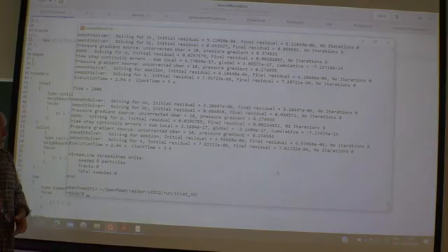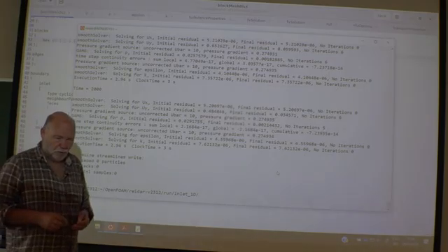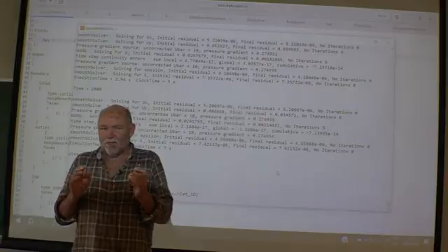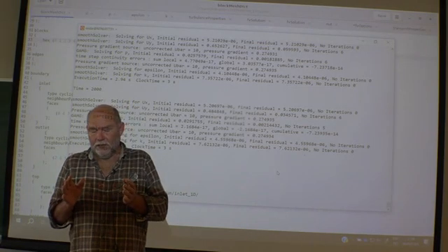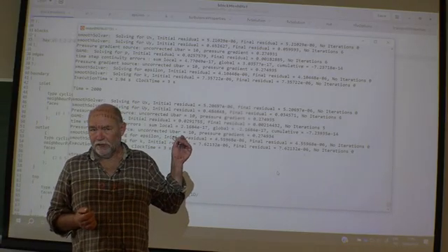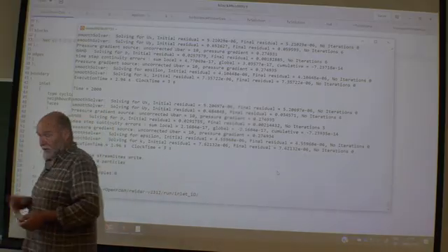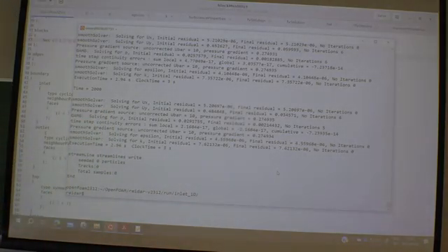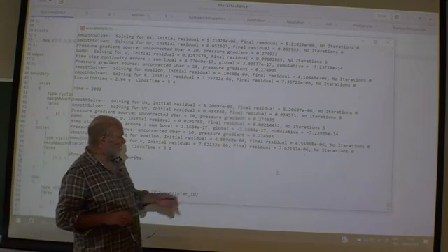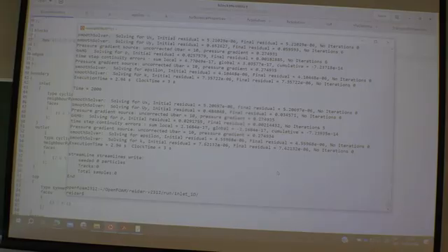The problem here might be actually the way he calculates a residual. Typically what he does, he creates a first residual for the first step. And then he uses that one as a scale. So the residuals are non-dimensional. And if your first residual is 0, then he scales towards 0. So that can be actually a problem with the residuals. We talk more about the residuals later. The other residuals here are actually quite fine. Okay, never mind. Let's have a look at the solution here.